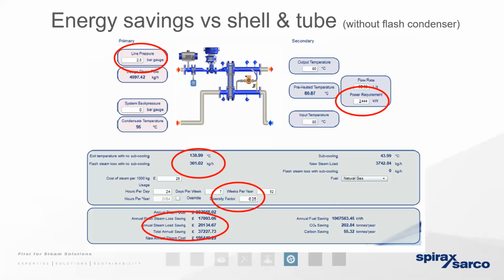So as the condensate left the heat exchanger and passed over the steam trap, there would be a fall in pressure downstream of the steam trap. Flash steam would arise. That flash steam would be vented away to atmosphere. It would result in a significant energy inefficiency. And we're going to cover that topic in a little bit more depth when we present our next topic in the opening weeks after Christmas.